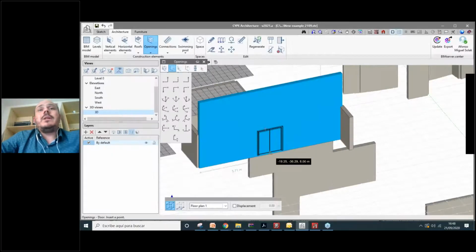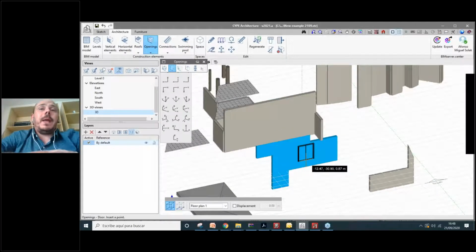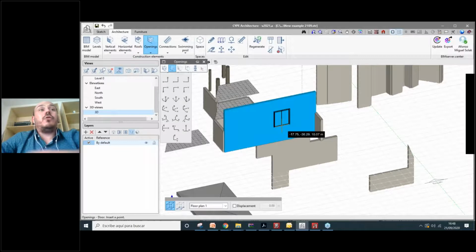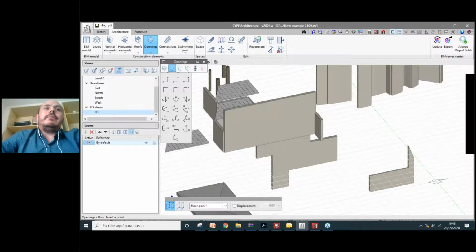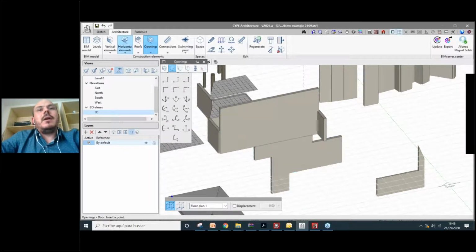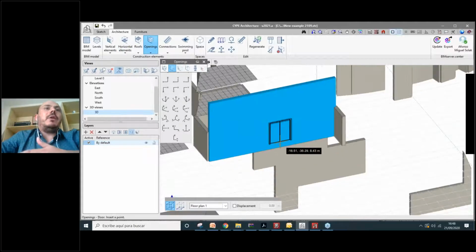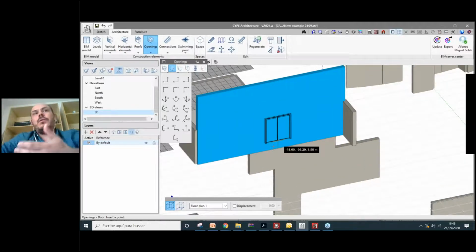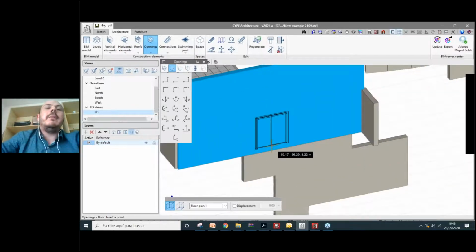And then we select one surface, which must be an architectural surface. So we must have a construction element, a wall or a roof. If it's a window, a roof window, it does not work with a sketch. So we must create this entity before, this IFC entity, this constructional element, this architectural element.